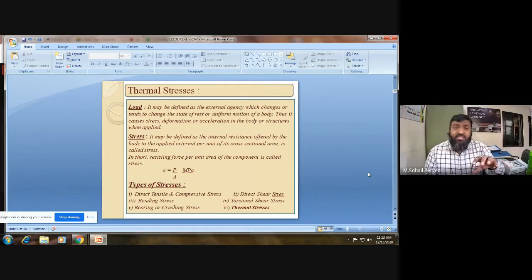Now, why am I insisting on this concept? Since we are much acquainted with the definition force per unit area, but that definition is a mathematical representation. Resistance has to come when some external load is applied. Now, where will it resist? Across its cross-sectional area. Why not length?